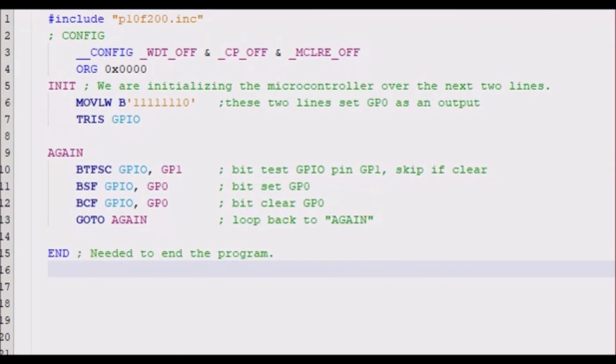So, as will be seen in the practical example, I use a push button which has pull up and pull down resistors on it to add as an input into GP1, and then I switch it out for a 555 timer circuit rather than a push button, so my finger doesn't get tired. That was a joke. Me having a tired finger was the joke part.